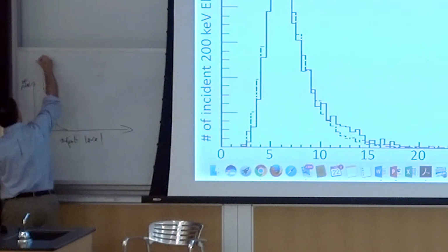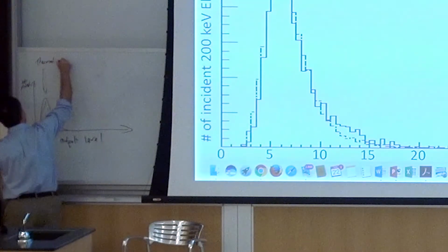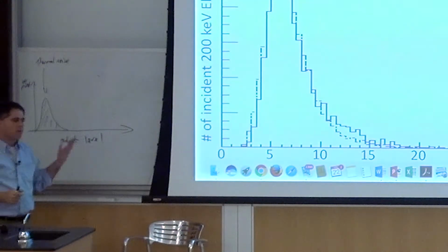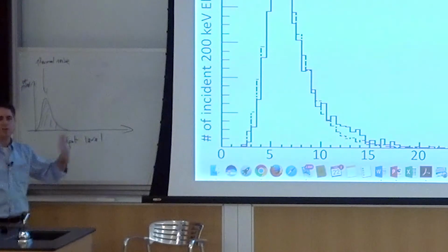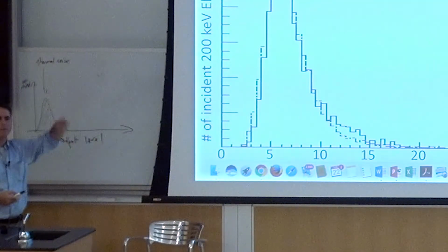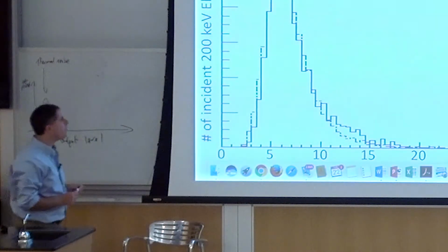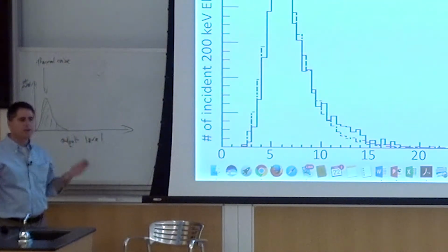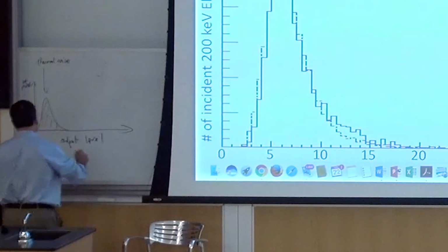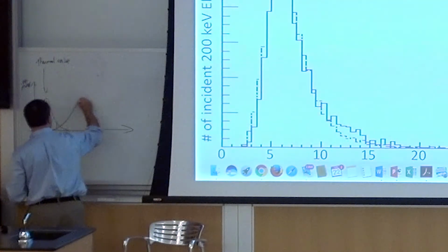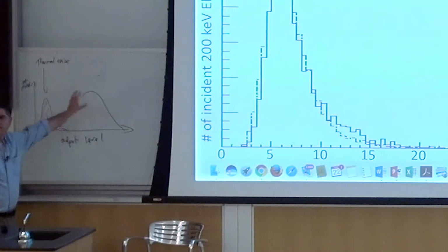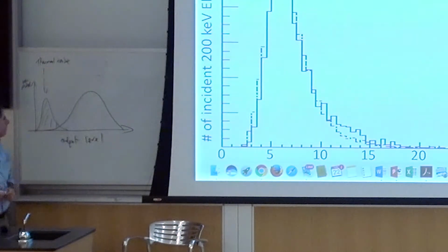This is the thermal noise, and that would be present whether or not you had a signal on the detector. This is just the dark noise in the detector, which is just thermal recombination because I'm exciting electron-hole pairs from the valence band to the conduction band. The second thing that you want is the signal generated by an electron, and that might be something that looks like this. This is just a generic output of a generic detector.